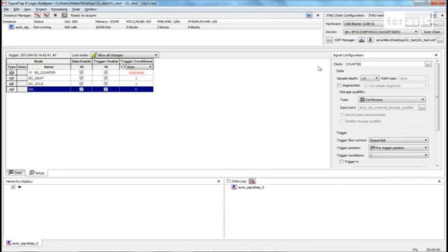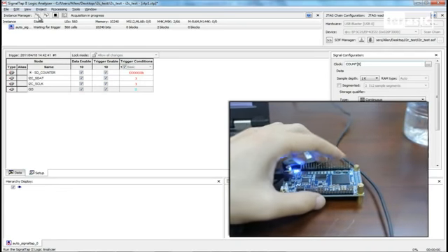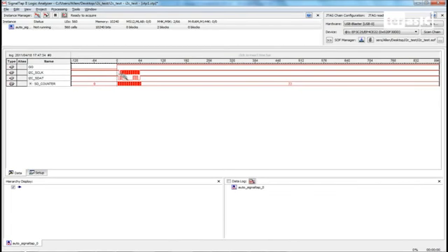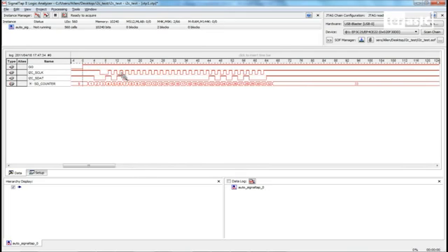Our sampling clock is twice the speed of our regular clock, so it's the 9th bit of count, and our sample depth is 1K. And since everything's connected, we'll go ahead and press program. And now it's ready to acquire. We'll acquire, wait for a trigger, and the go will go when we press key 1. So now we can see that we have our I2C signal.